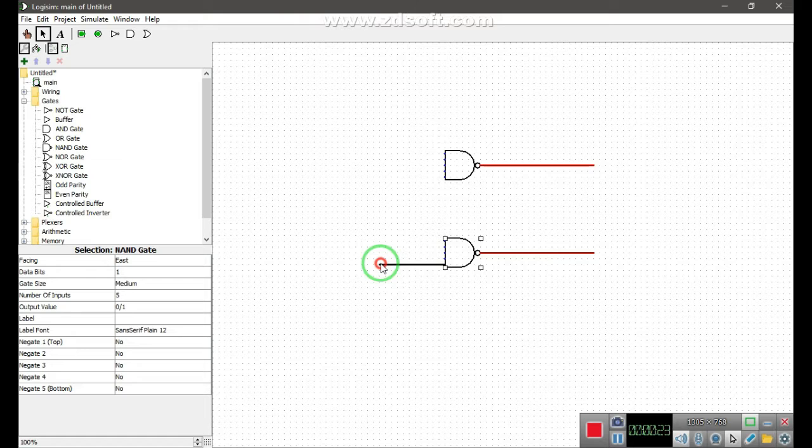This device consists of two inputs, one called the set, capital S, and another called the reset, capital R, with two corresponding outputs, Q and its converse or complement, not Q. So consider the set state in the circuit shown in this example.